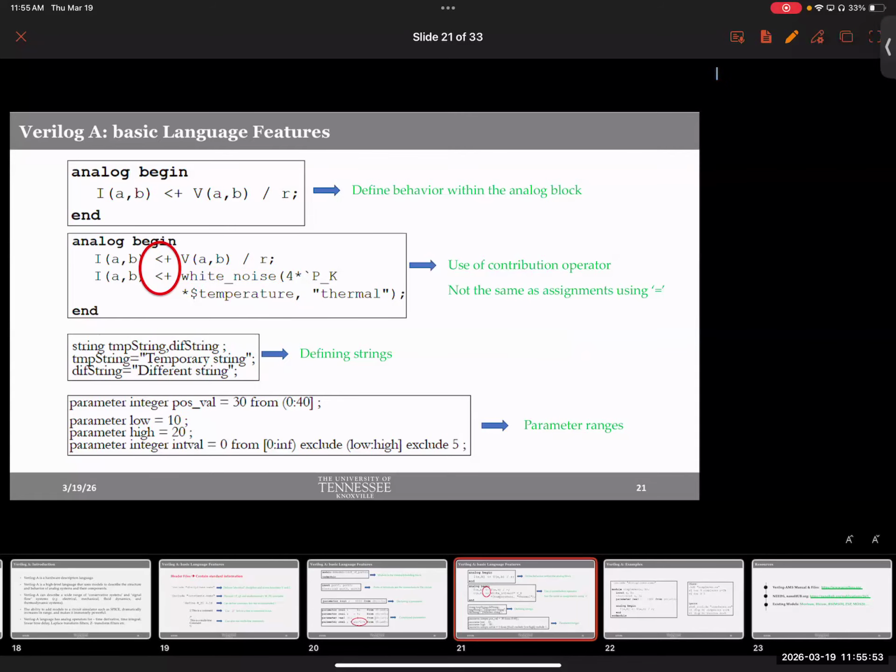So it is generating white noise based on the equation that we know of white noise, and it is a thermal property. So it is allowing you to incorporate this thermal fluctuation within the device that was otherwise very simple to work with. So now that you've incorporated this contribution as well, when you simulate in SPICE and set a temperature, that will have an effect. Otherwise, if you just go with this model, who cares? If you change temperature, nothing changes. Are you all okay so far?